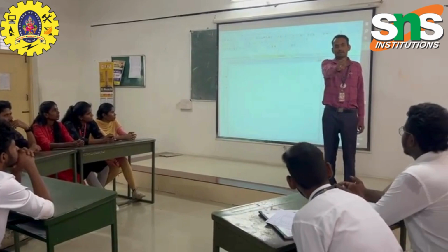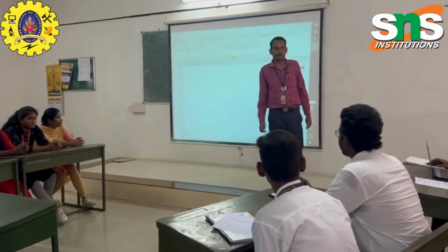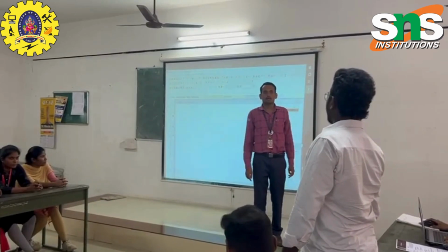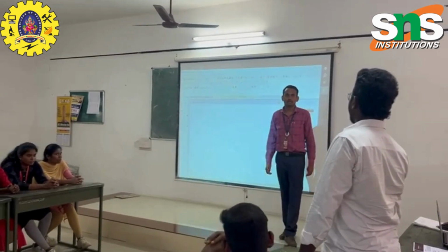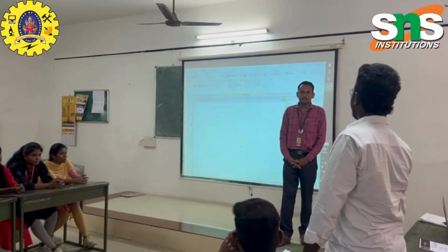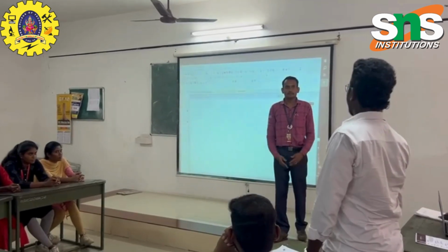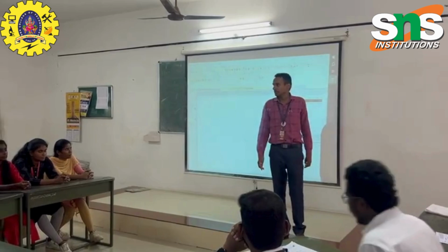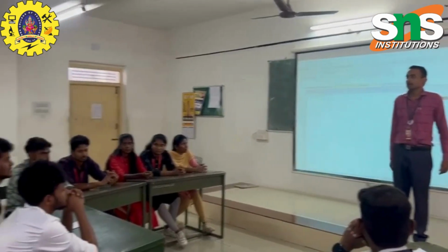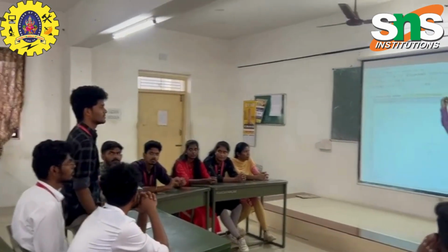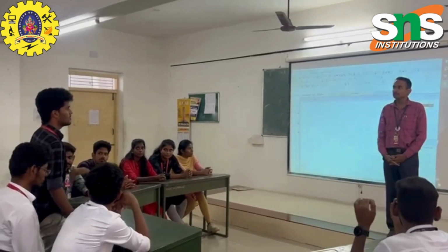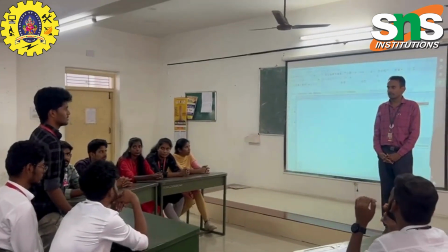So Arun, can you list out what are the steps involved in designing of STAAD.Pro? First we have to create the nodes. After that we have to add the beams. After that we have to assign the node. Then post processing analysis. What are the results we are going to get as output in STAAD.Pro? Shear force and bending moment.